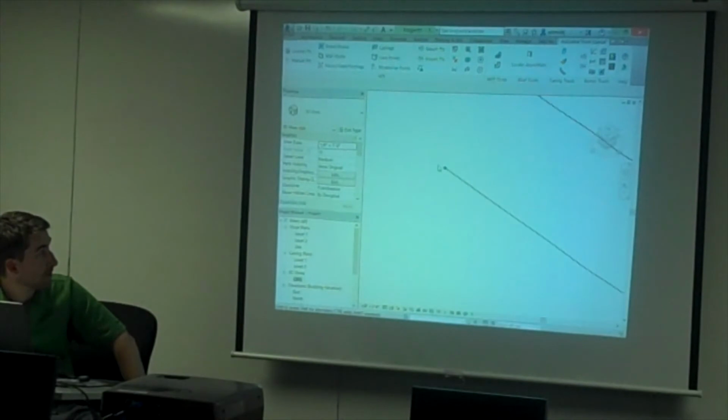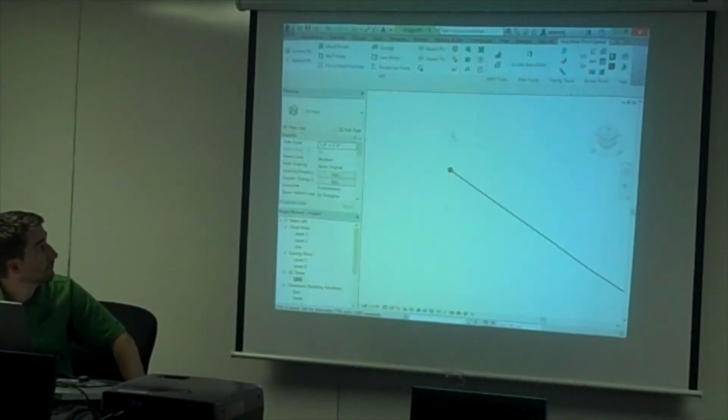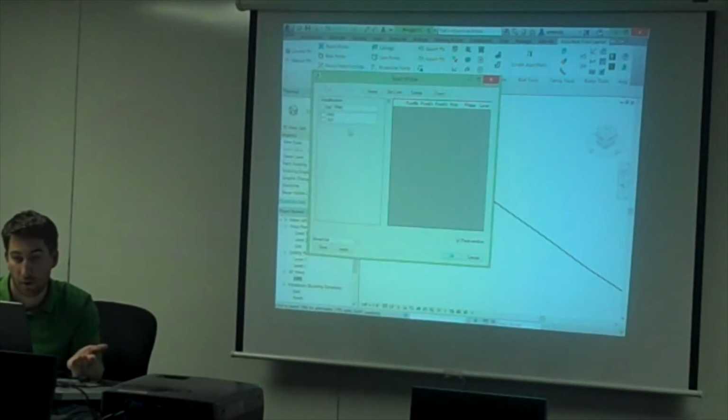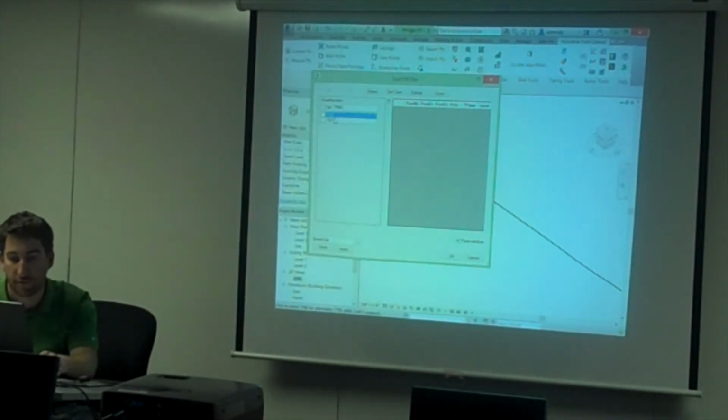And then inside the product here, you can see we've got these little 3D points. And so if we look up here, we should have a couple of points that it shows us. So it automatically decided there's a standard that you can set in the system for stakeout points to be at 1,000, and for plumbing points to be at 5,000, and electrical stuff to be at 7,000, so you can sort of stratify that stuff.